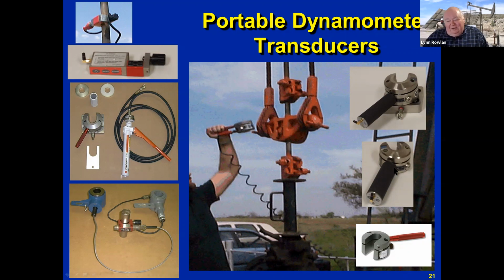So the 30K load cells, the throat here is 1.5 inches, and it'll go around a 1.5 inch polished rod. And so to put this on the well, you have to put a suitcase on the well and rest the entire rod string weight stacked off and not damage your packing. And then make a gap that's more than 3 inches to put this in there, and then you release this load back onto the load cell. Well, that's kind of a hassle.